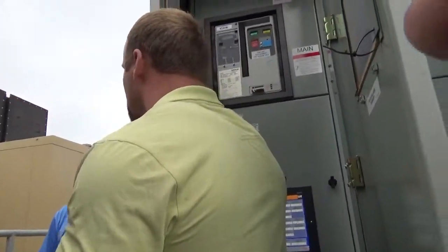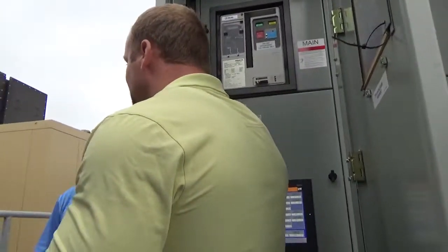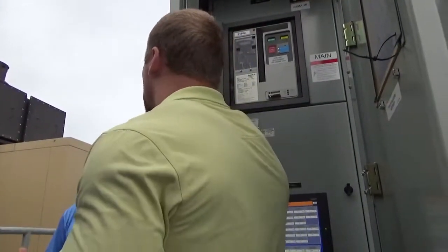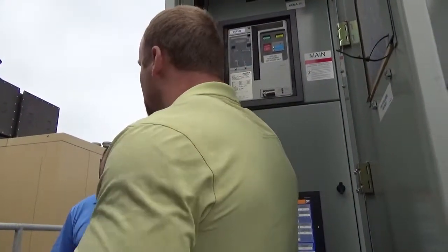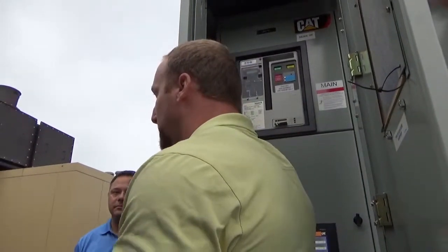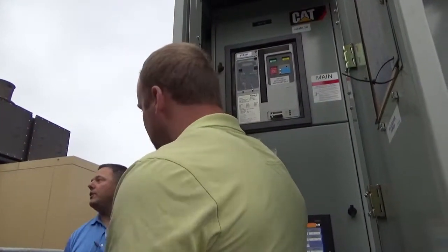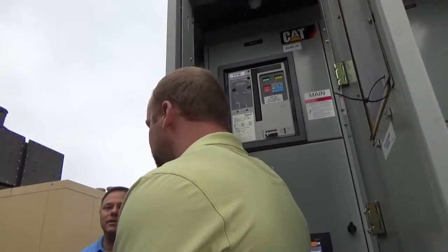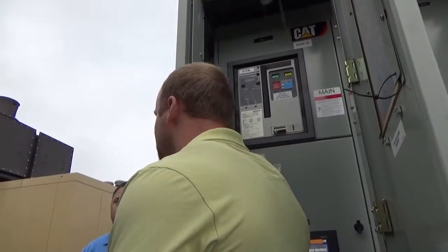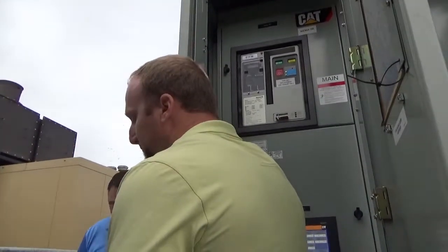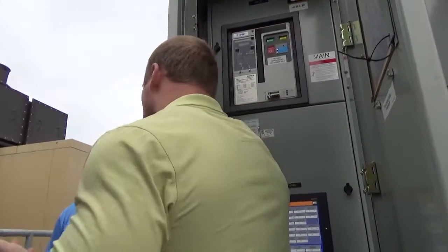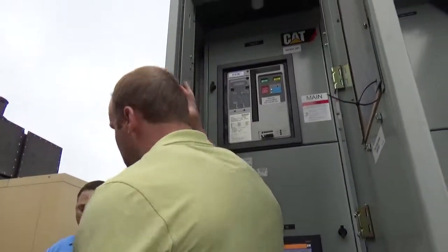But you know what? If you don't have a lot of site load, there's some sites that don't even have a load bank. And if you don't have a lot of site load and you don't have a load bank, it'd be like driving in 4th gear up a hill, chugging it. It's just not good for the site. You don't want to wet stack it. That's what I'll recommend to our boss for sure. I think Gen Demand is a great feature. Some people don't like it, but to me, I think it's a great feature.